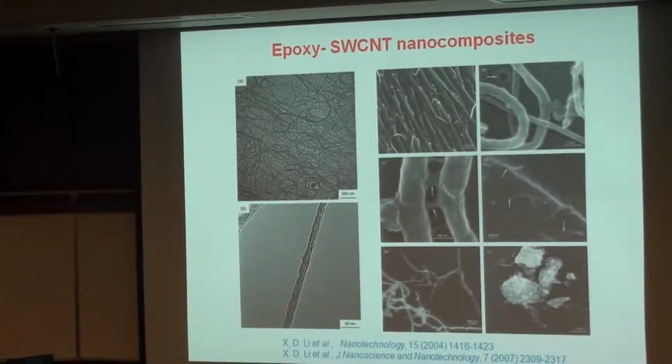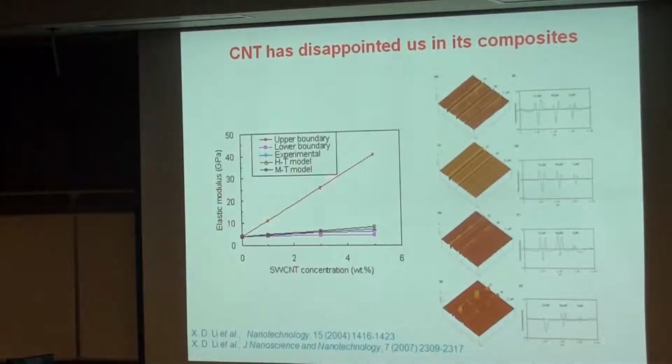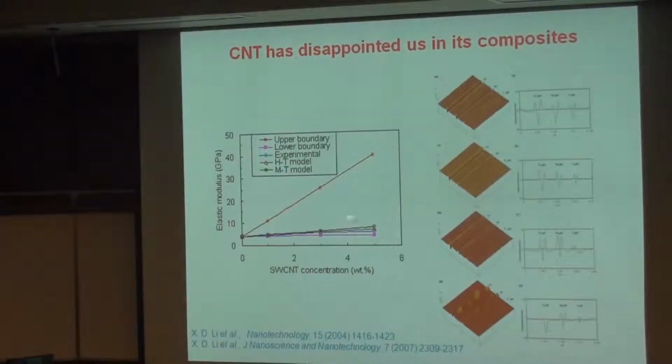Only the outer-layer carbon nanotubes, well bonded with the matrix, truly carry the load and do the work. The other carbon nanotubes in the core are defects. Although we saw pulling out and bridging effects, when you try to increase the carbon nanotube content from 1 weight percent to 3 weight percent, they tend to agglomerate to form carbon nanotube bundle blocks.